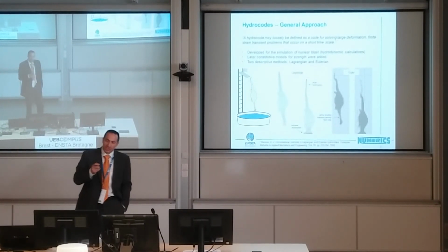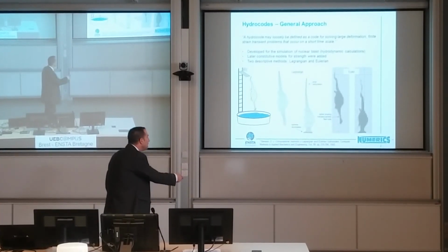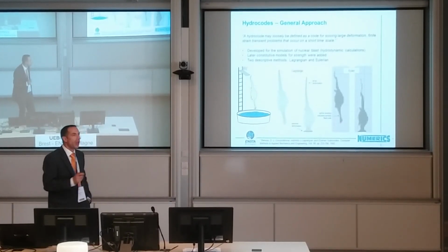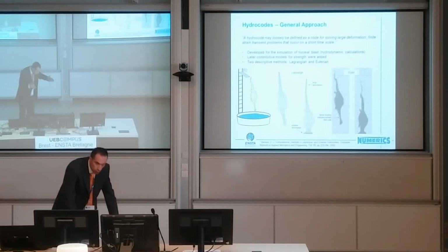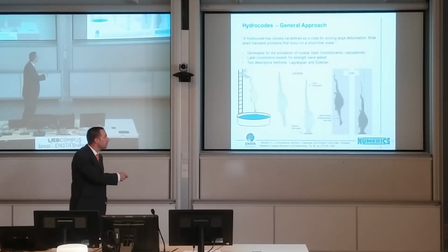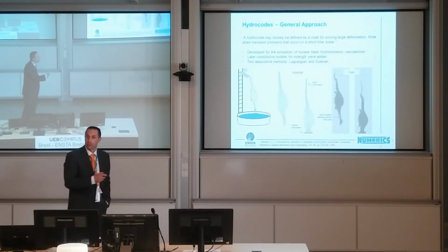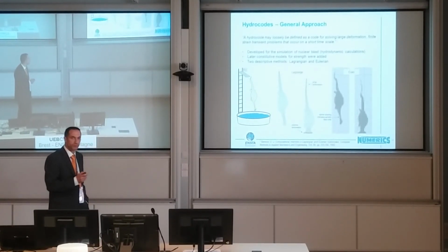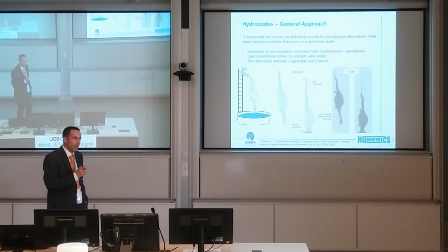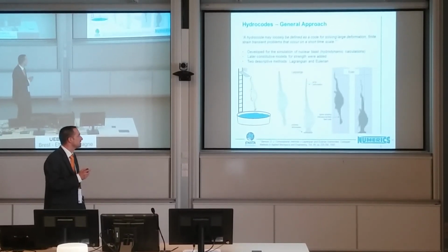And the second way to look at it is to keep the mesh fixed in space and let our dinosaur actually jump through the mesh. So here the material goes together with the mesh, here the material goes through the mesh. Two different points of view should theoretically give the same results.